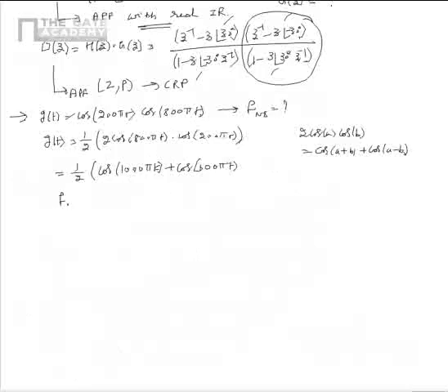From this, we can say that the bandwidth of g(t) is equal to 500 Hz. From this, the Nyquist sampling frequency of g(t) is equal to 1000 Hz, which is 2 times fg. So the Nyquist sampling frequency of the given signal is 1000 Hz.